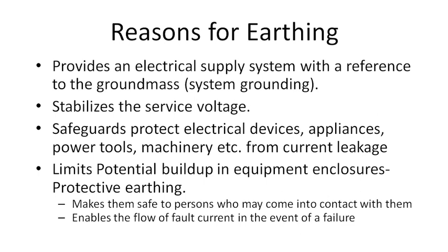Reasons for earthing. Normally, earthing provides an electrical supply system a reference for the ground. In case of a three-phase system, we will connect the neutral point to the ground so that the neutral potential will remain within safe limits. This eventually helps in stabilizing your service voltage. These two points come under functional earthing.